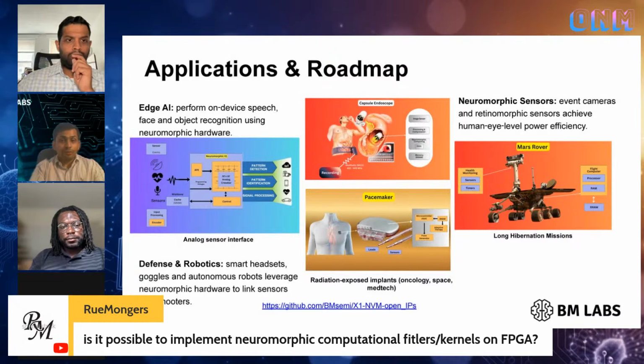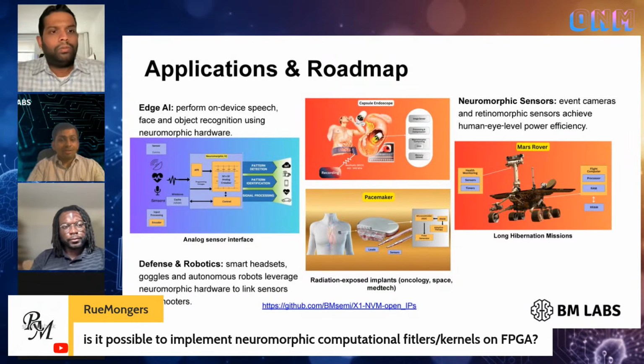A few people have used it for applications like pacemakers, because if you Google it, ReRAM is radiation hardened. Maybe the Caravel SoC might not be radiation hardened, but our IP fundamentally can be qualified for radiation hardened after a few iterations. The reason is that it doesn't work on charge. Charge migration using tunneling is how MOSFETs work. It actually works on physical ions moving. So it's a solid filament, like a metal filament, right? So it can take more radiation and higher temperature and things like that. So that's why people are using it for medical applications.